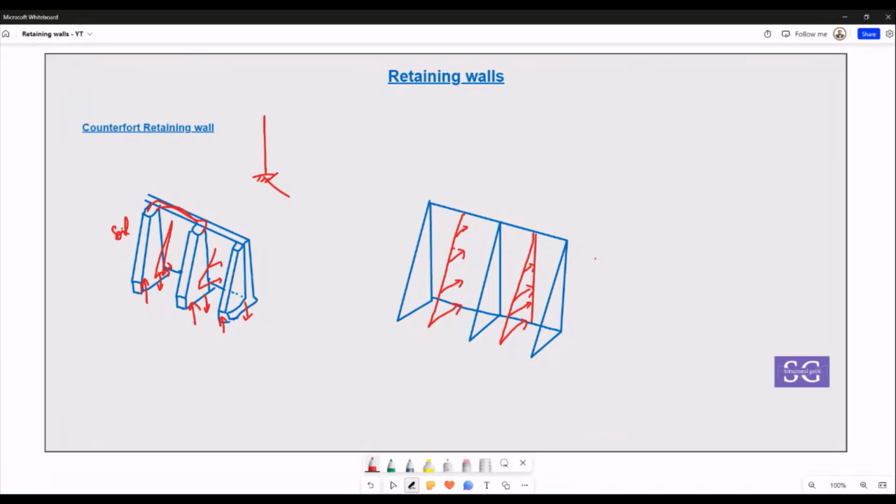If we try to understand through this diagram, a 2D frame diagram won't be used here, we'll have a 3D sort of diagram. The load transfer is such that we get a horizontal force on this surface, applied as a one-way action. Let's assume no load is taken by the bottom, because we are saying there is no fixity at this place.